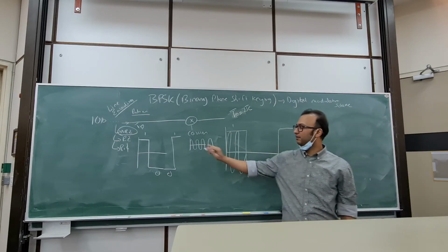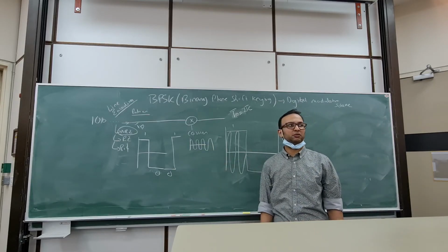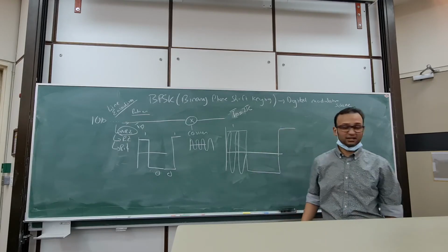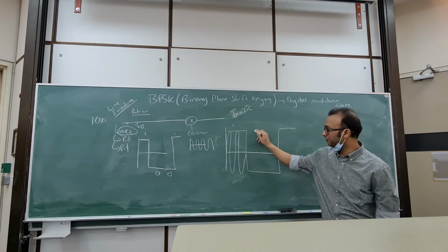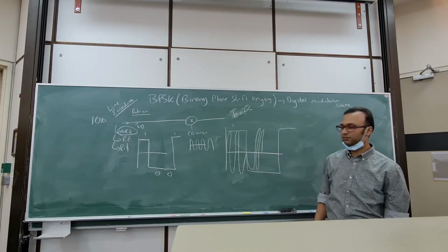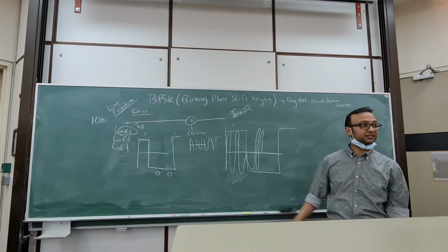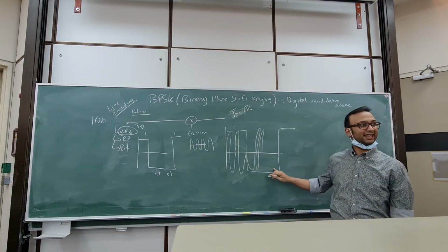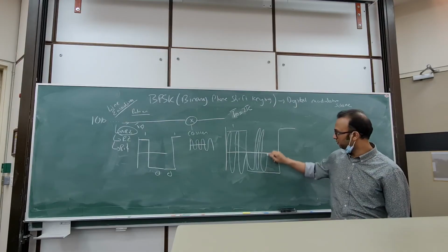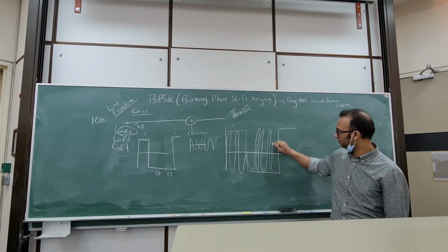Now when the carrier is multiplied with minus 1, what happens? A 180 degree phase shift, right? So instead of starting from there, it will start from here. 1, 2. It's a W shape, yes. Over here again it's a 0, so it will start from negative. 1, 2.